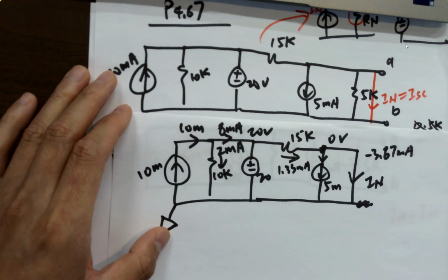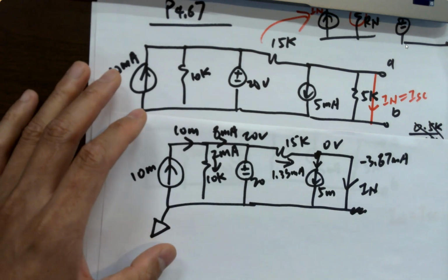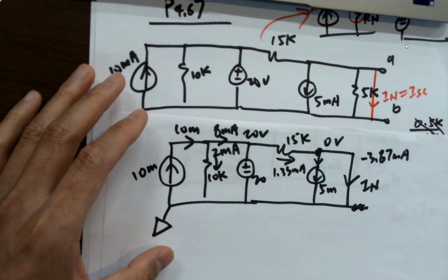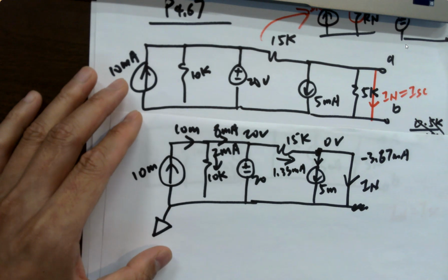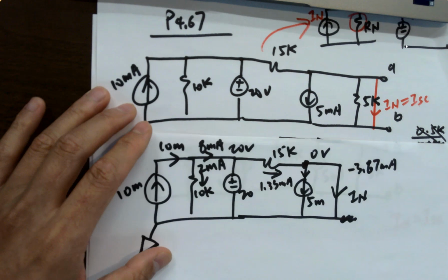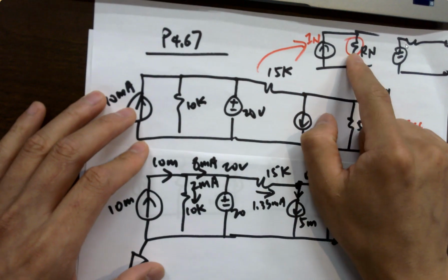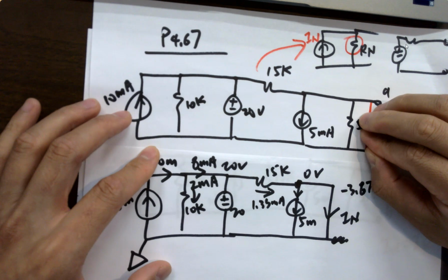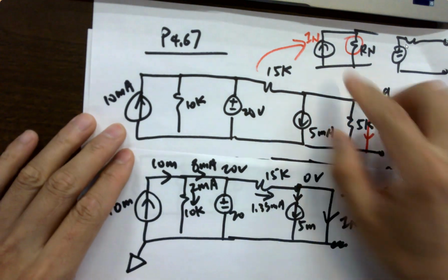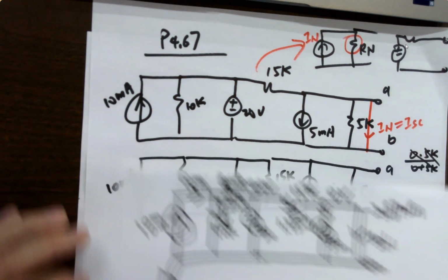See the limitation here? Oh, we haven't reached the limitation yet. So see the perfect methods that I just introduced? It's been working for my whole life. Okay? No problems at all. If you use this method, it's going to work. All right, Norton's equivalent. How do you find the Norton's equivalent? Just two steps, right? First, find Rn: remove the load, look back, short the voltage source and disconnect the current source. Find the resistance. And how to find IN? Draw a wire, and the current flowing through it is IN. We just got it, and they are both correct.